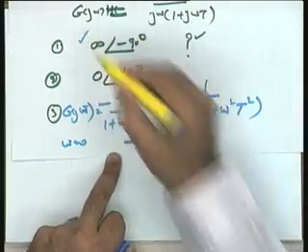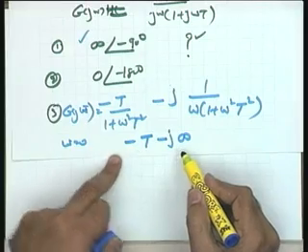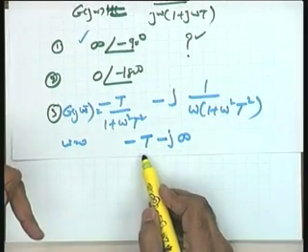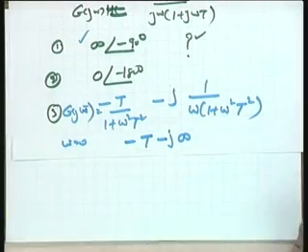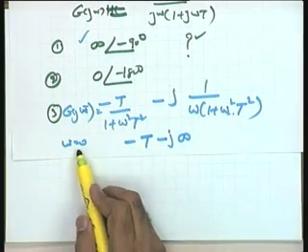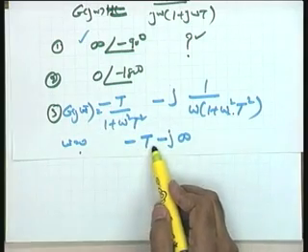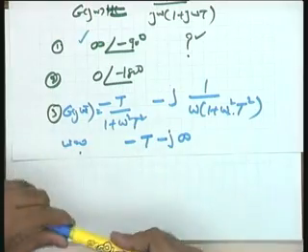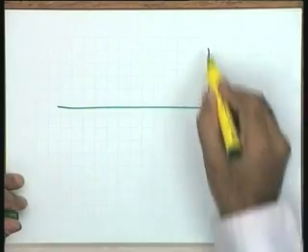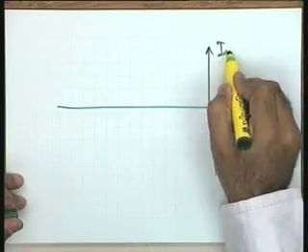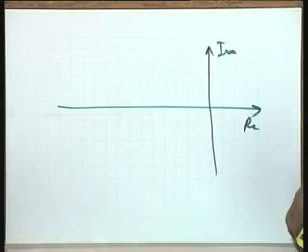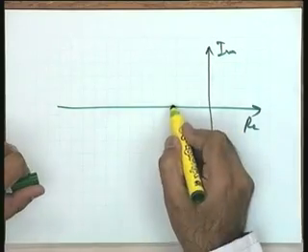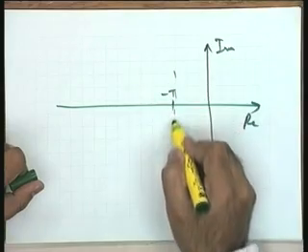Actually this omega is equal to 0 picture means it goes to infinity along the asymptote drawn at the line minus t, 0. I need your attention please. If I substitute omega is equal to 0 in this particular vector, I find it is minus t minus j infinity vector. So if I make a sketch, the sketch is the following. Though this does not matter, if you would not have realized this, you would not have got this information, then also the stability answer would have been the same. I take this point as minus t point.